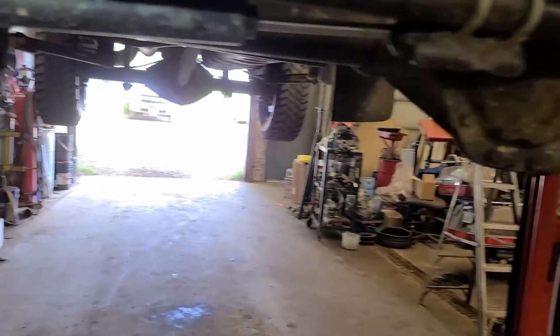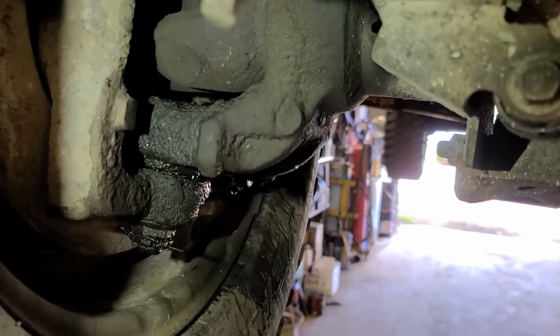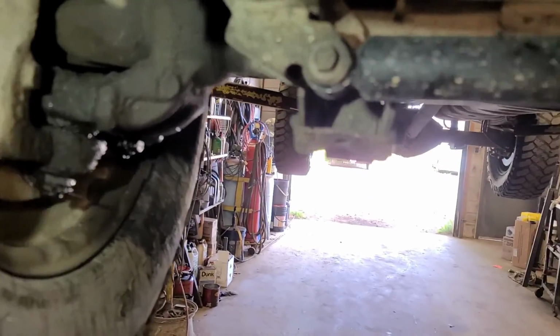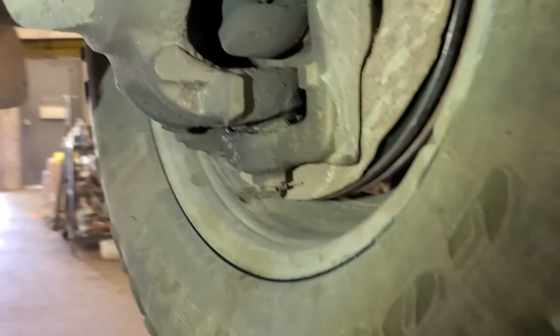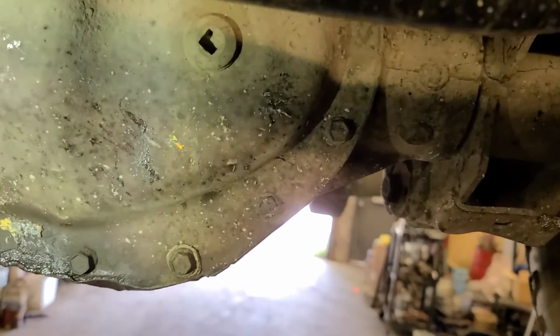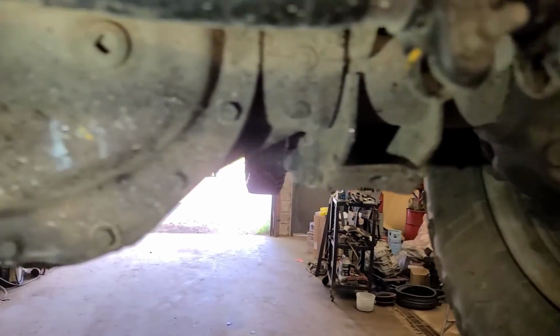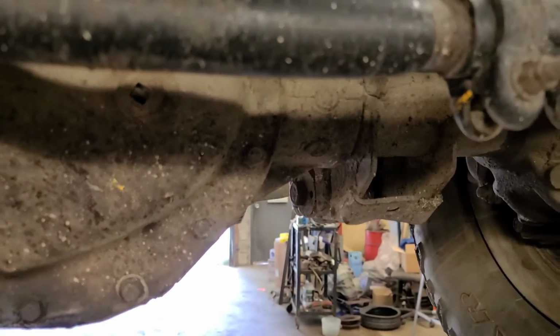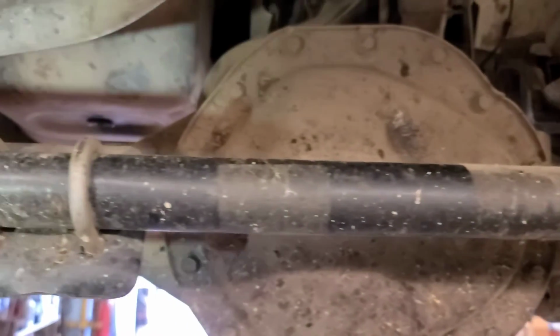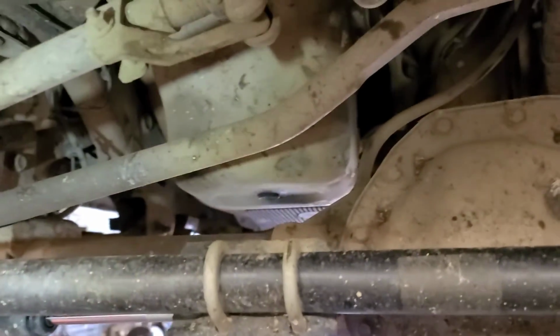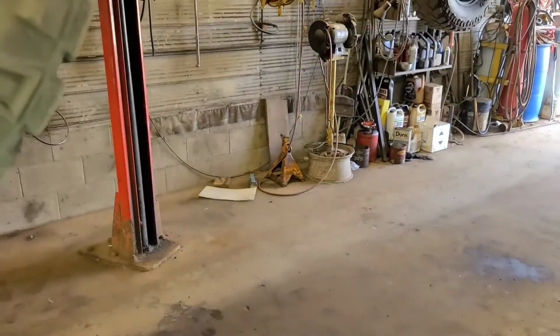And I see he's got a front axle seal leak on the right side, left side seeping as well. And if you're going to do one axle seal, you might as well do them both, because you've got to pull the differential carrier out and both axle shafts out anyways. These axle seals are in here inside the housing, but that's a job that he can do. I suppose we'll look at the ABS quickly to see if there's power and ground to the ABS module.